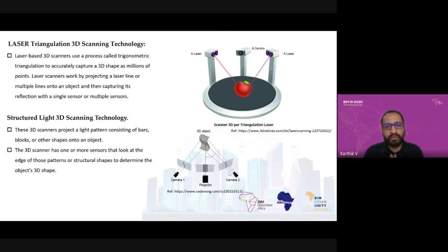So you should know how to separate the project and the setup, and only then can you work with the 3D model. If your point cloud is huge, don't bring it into your authoring tool. Your authoring tool may crash or not open, or you can't rotate it. A lot of things will happen. So we have to clean up the point cloud, whether it is laser-based or lidar, whatever. Make it into small pieces, then we bring it in for checking purposes.